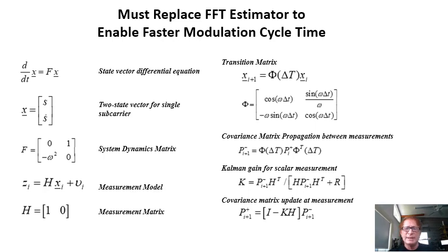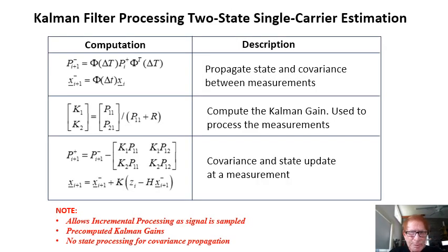The complete set of matrix math for the new algorithm is totally defined by the underlying math model and its noise statistics. We have summarized the complete Kalman filter algorithm here. We have also simplified the Kalman gain math and the covariance update math based upon the single measurements and the form of the measurement matrix that includes only ones and zeros.